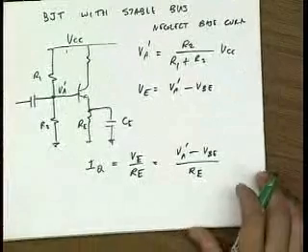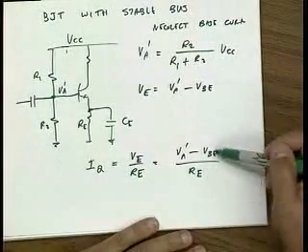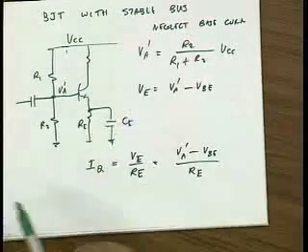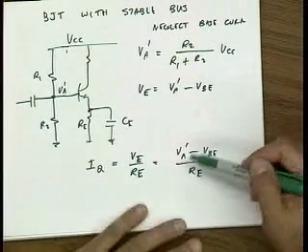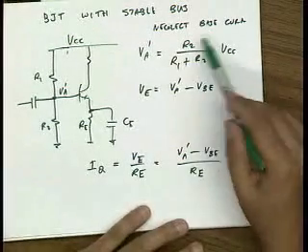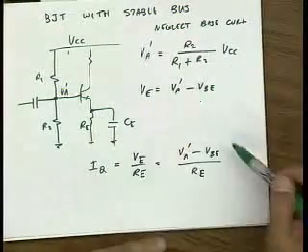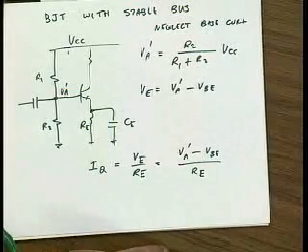The idea is that this is a good biasing scheme because VBE is very insensitive to the actual current value, since it's a logarithmic function of the current. And VA, because base current is very small, is just fixed at some fraction of VCC. So this gives me a nice collector current, independent of temperature and bias.